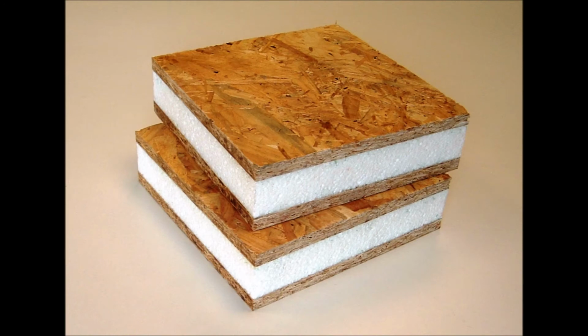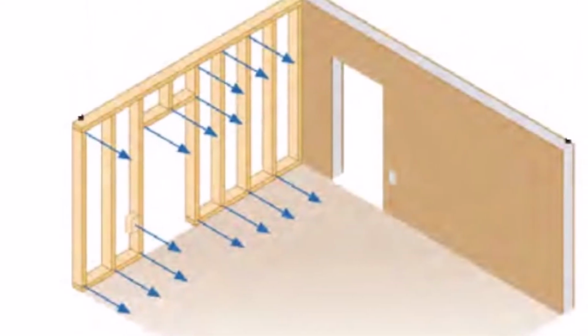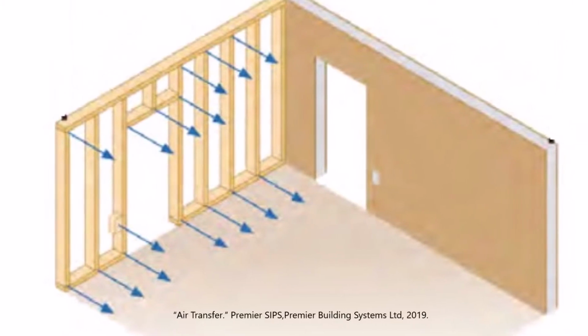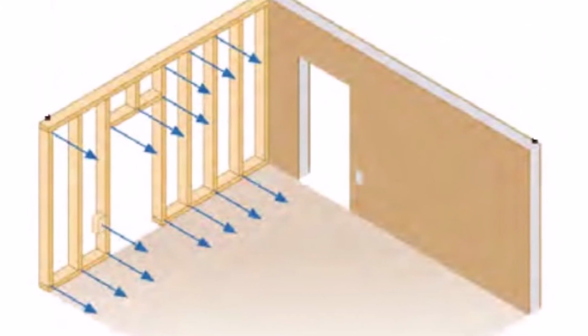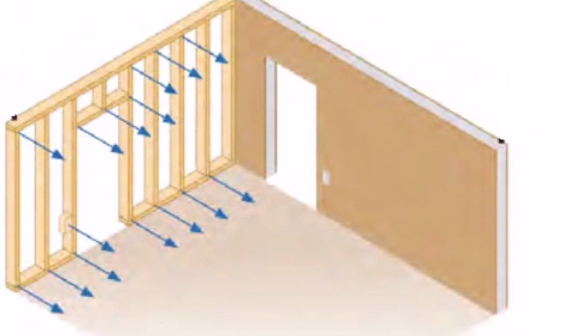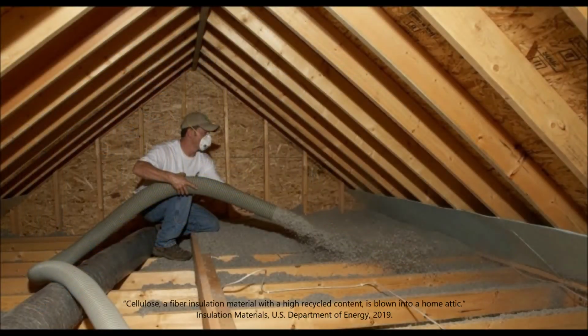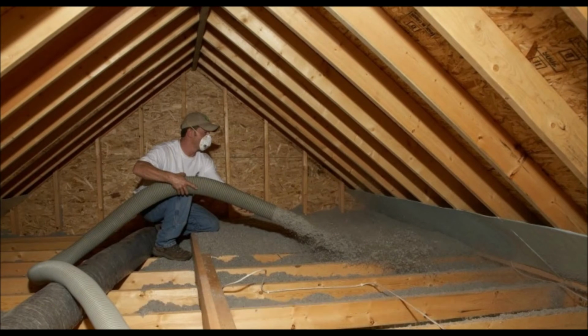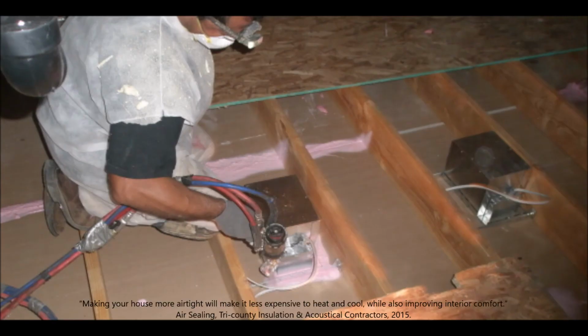The exterior walls of the home are structurally insulated panels. They are made of polystyrene foam core between 2 sheets of oriented strand board. Structurally insulated panels reduce air leakage and thermal bridging as there are no studs in the wall and therefore increase the insulation value. The attic is insulated with blow-in cellulose, achieving an insulation value of R66 in the upper clear-story area and R45 in the lower clear-story area.